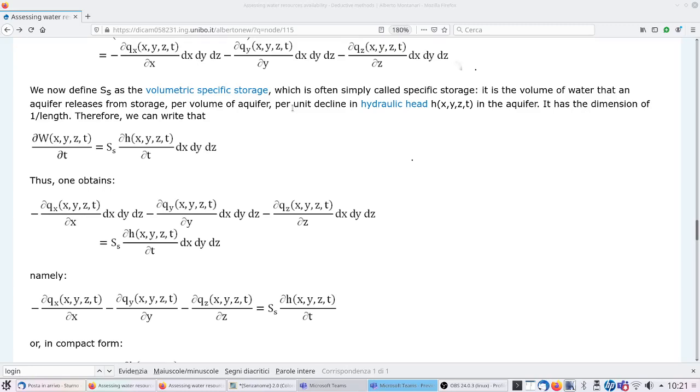If the aquifer stays saturated and the volume of the aquifer remains the same, because we refer to a unit volume, then the volume doesn't change. The aquifer remains saturated. Why is water released? What are the processes, again, leading to release of water? There are two components. If you decrease the head, you decrease the pressure in the aquifer, because remember that you have a column of water up to the level of the head that is pushing over the aquifer.